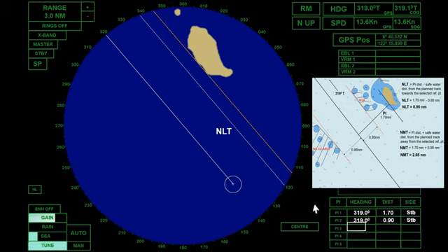Let us set the not more than line in PI3. The heading is 319 degrees. The distance is 2.65 nautical miles. And the side is starboard side, since the location of the reference point is on the starboard side of the planned track. The not more than PI line is already displayed in the radar screen. The distance set in the radar is based on approximation. Since this is just an animation, I am not using the actual radar.